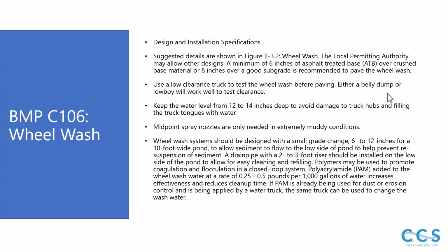Keep the water level from 12 to 14 inches deep to avoid damage to truck hubs and filling the truck tongues with water. Spray nozzles are only needed in extremely muddy conditions. Wheel wash systems should be designed with a small grade change, 6 to 12 inches for a 10-foot wide pond, to allow sediment to flow to the low side of the pond to help prevent resuspension of sediment. A drain pipe with a 2 to 3 foot riser should be installed on the low side of the pond to allow for easy cleaning and refilling.